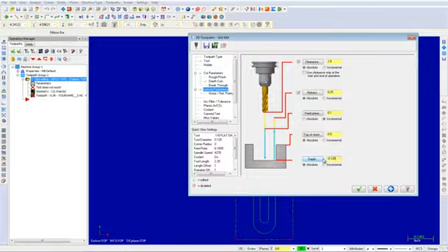I will now take a brief moment to explain a few of these parameters. Clearance sets the height at which the tool moves to and from the part. Retract sets the height that the tool moves up to before the next tool pass. Feed plane sets the height that the tool rapids to before changing to the plunge rate to enter the part. Top of stock sets the height of the material in the Z-axis. And finally, depth determines the final machining depth that the tool descends into the stock. Once the parameters have been adjusted, select the OK button to exit the slot mill parameters.